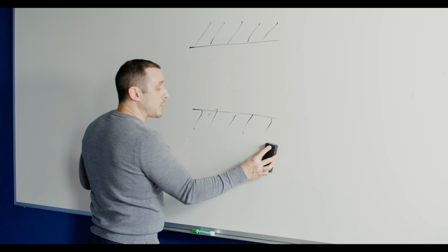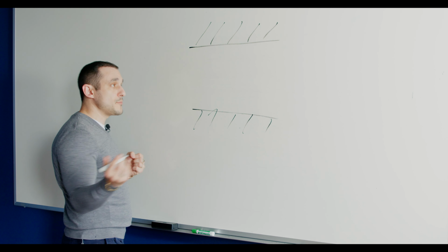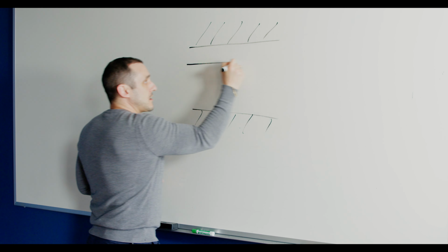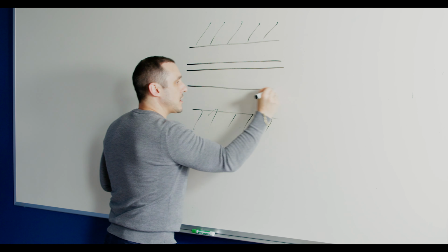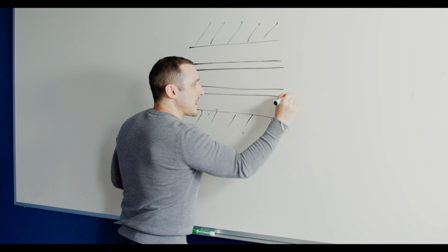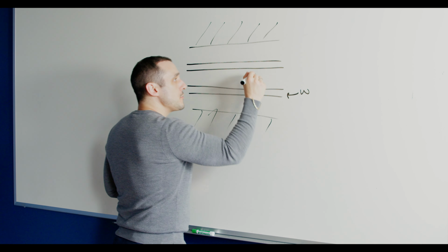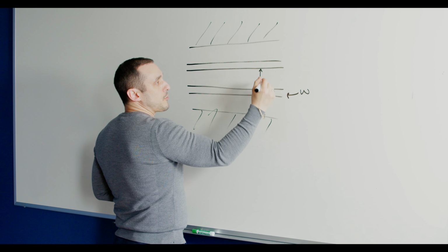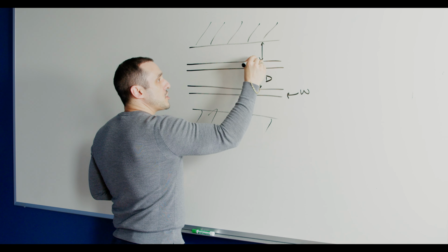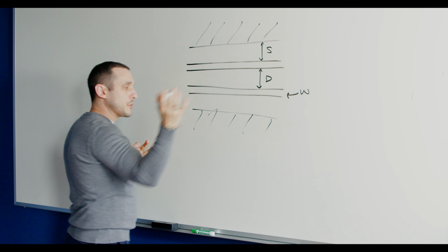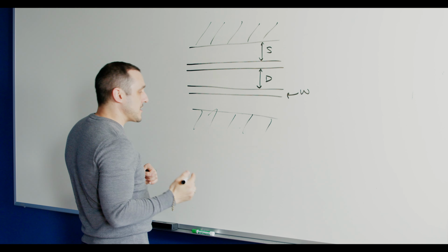We saw the example on the screen with the USB lines. So in that case, let's just suppose we have two traces here, and these traces are part of a differential pair. The traces have a width of W, and then there's some separation between them, which we'll call D. And then we have our separation to our grounded coplanar copper pour, which we'll call S.